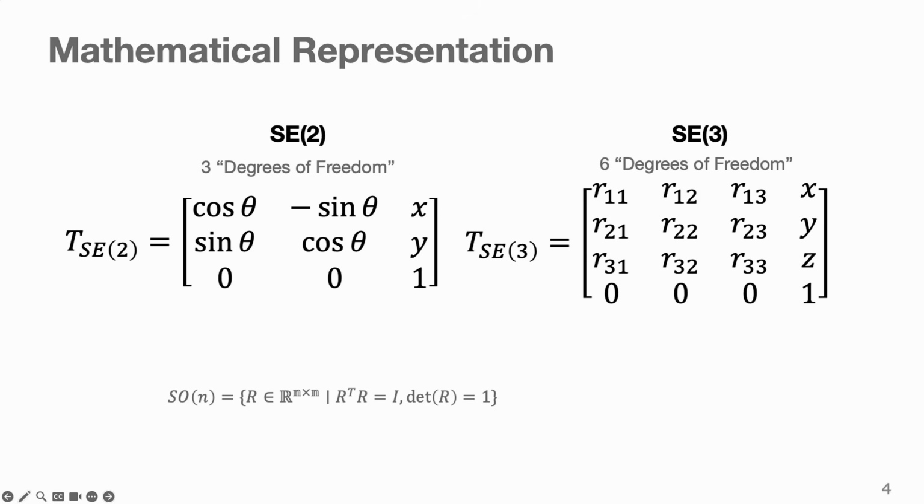And maybe one thing to sanity check on the math here is that in order for these matrices to be valid rotation matrices, they have to satisfy two properties. First, the matrix needs to be orthogonal, meaning that its transpose is equal to its inverse, and the second is that it also needs to have a determinant of 1. This is not a math trick, but just ensures that when the robot rotates, it doesn't accidentally stretch or anything, so it remains a true rigid body.